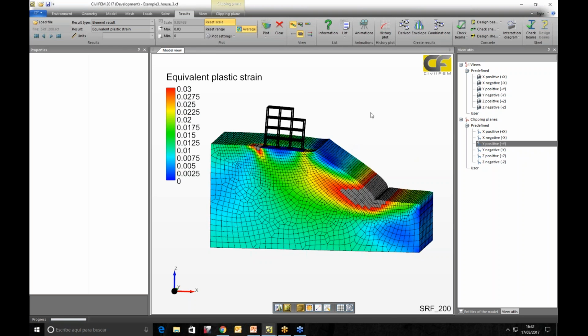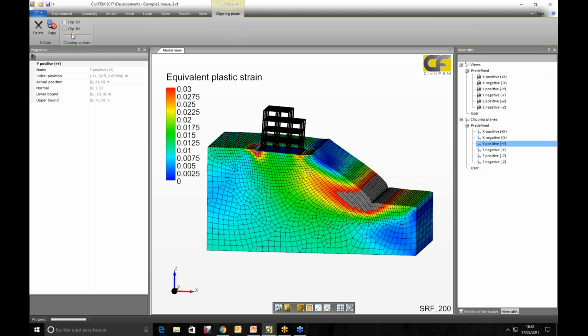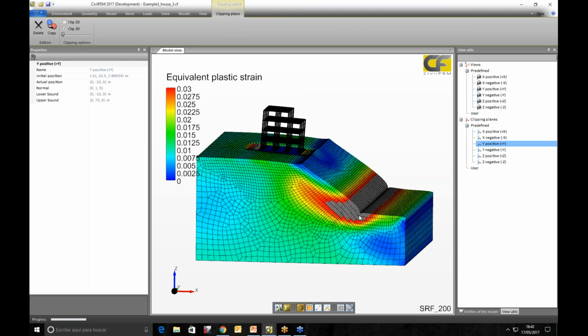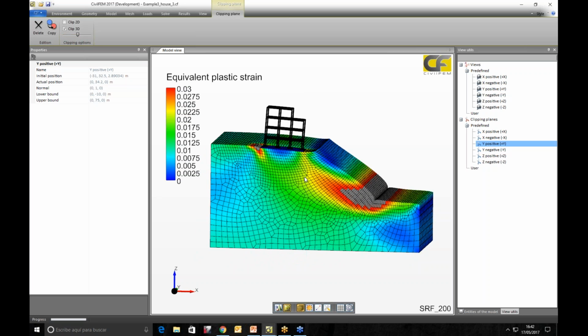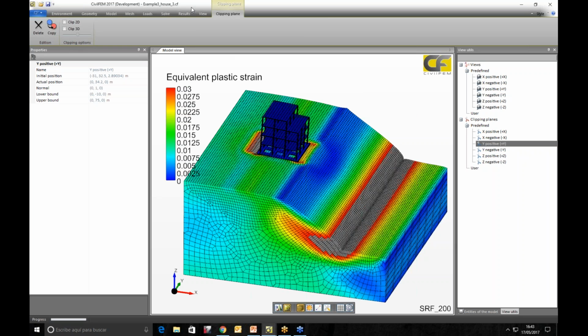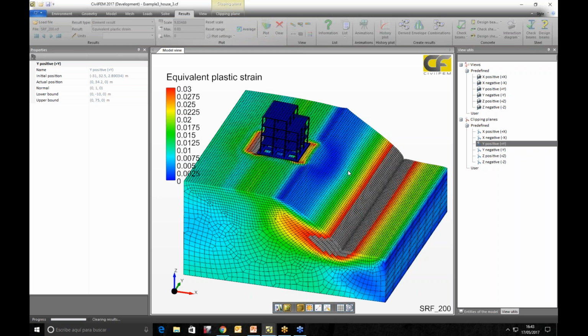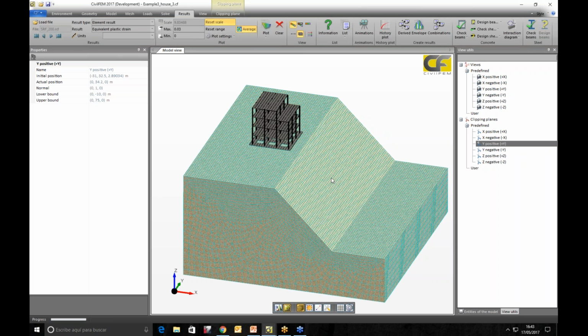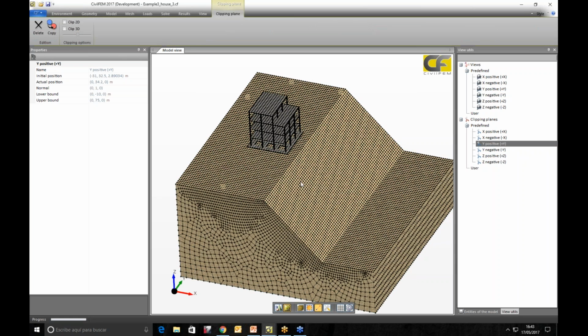We can see here that the yielding surface is almost finished on top in the other zones, but under the building the yielding zones are closed and the instability happens. And also, if we plot displacements on one of these nodes, we can plot displacements versus safety factor.